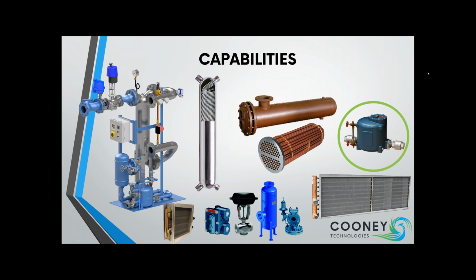And a few years back, the motive force condensate steam pump was invented. It also has a float inside, and it's really powered by motive steam in the top of that unit. When the condensate fills that, the float level rises, opens up a steam valve on top, and the steam system pressure pushes the condensate out past the downstream check valve to prevent any backflow, and depending on your motive steam pressure, it would send that over to your boiler room.